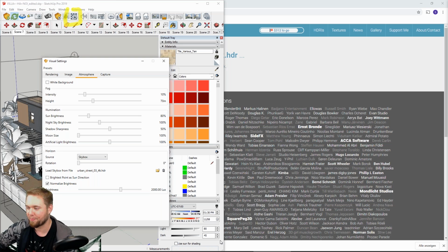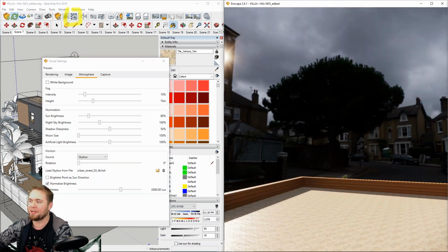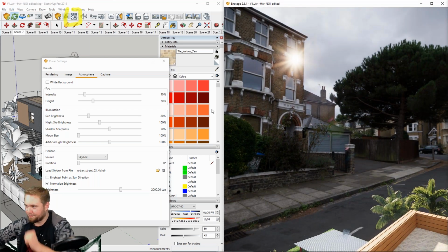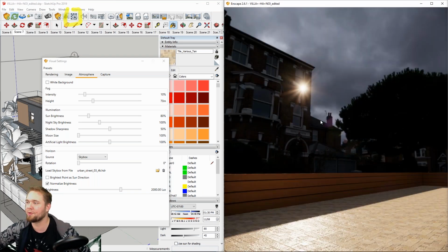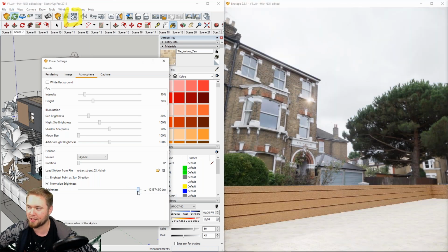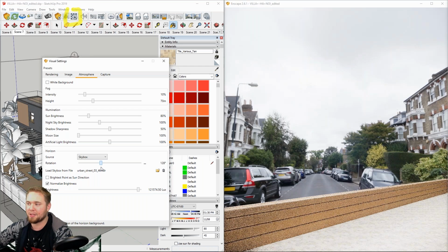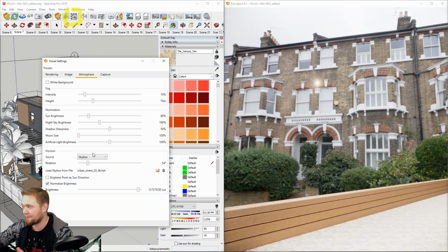All right, my bad. So we have a skybox now applied to Enscape. That's a different one, but it doesn't matter. By the way, you can control the brightness of your skybox very conveniently also down here with this slider. And you say that rotating your skybox does not seem to work. And if that's the case,